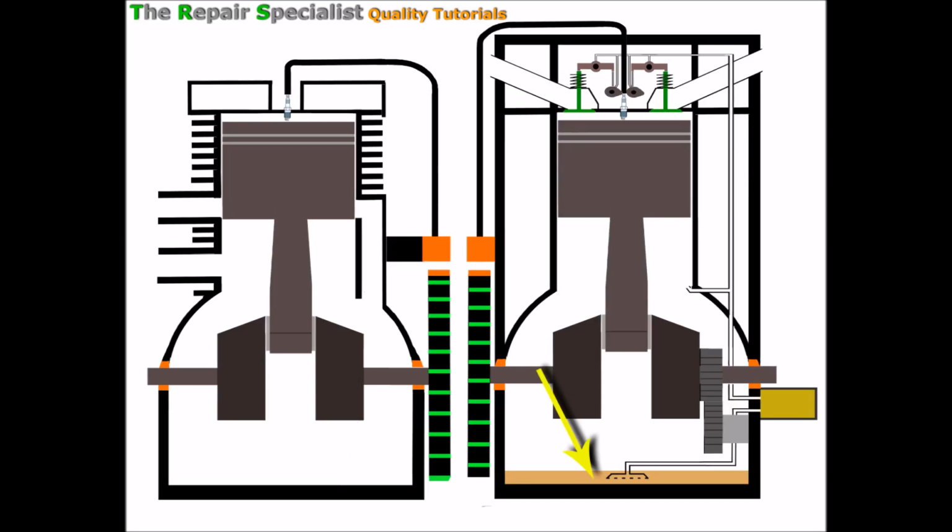So we'll start with the four-stroke. As well as giving that space for the turning of the crankshaft, we've got the oil reservoir underneath here for the four-stroke of course, because we have to put oil in a four-stroke engine. And of course when the engine's not running, the oil just sits here, but when the engine's running it's sucked up this pipe through this filter here and up right through under the piston and up to the top here into the rocker area where it lubricates the rocker arms, the valves and the camshafts, etc.